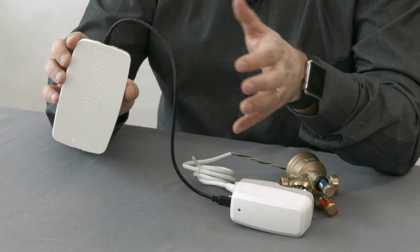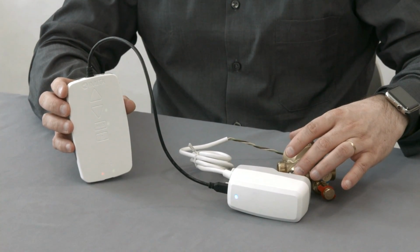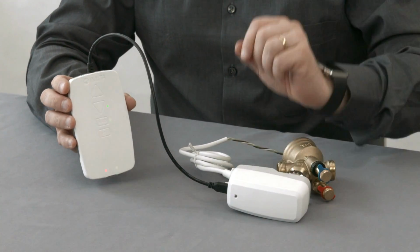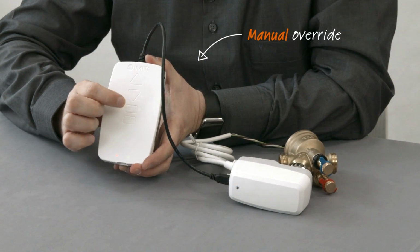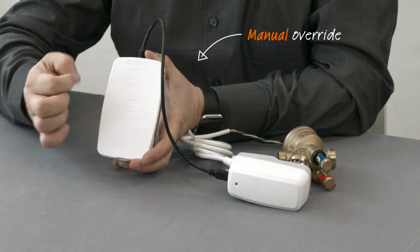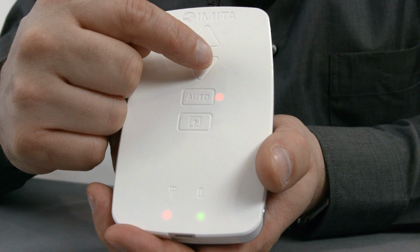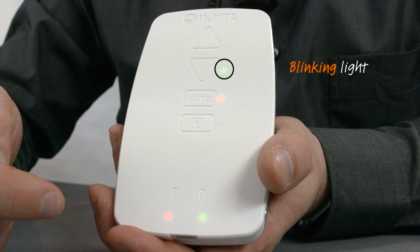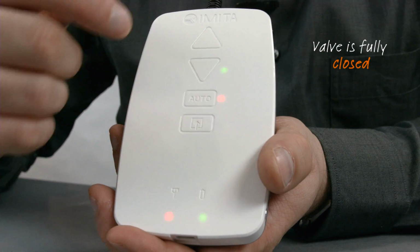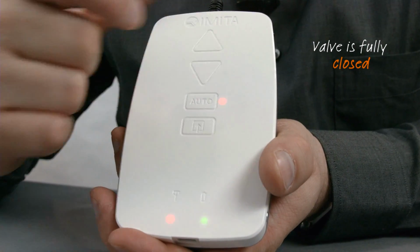For instance, if you want to measure the flow through the valve, you would need the valve to be fully opened, and the easy way to do that with the dongle is simply to press on this auto button here to switch to the manual mode as the red LED is indicating. I can see from the LED blinking there that the actuator is already in the fully down position, so I will request it to go up by pressing this up key.